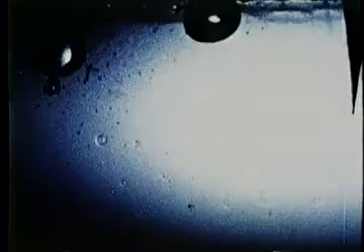These bubbles were formed in the low-pressure region near a body of revolution. Only a small portion of the flow field is shown. These bubbles were formed in the interior of a water sample subjected to an alternating pressure field. If such cavitation bubbles remain spherical throughout their life history, extremely high pressures would be developed upon collapse when the bubble is almost microscopic in size. Estimates indicate the pressure produced near the position of minimum radius is of the order of thousands of atmospheres.